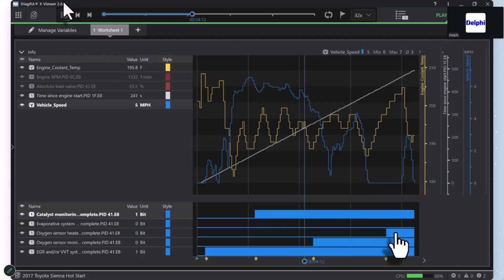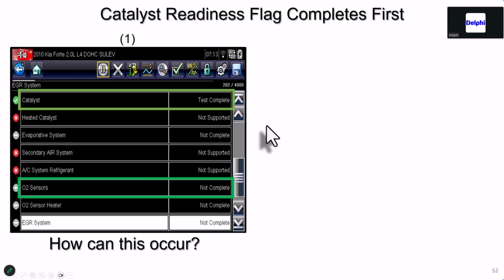I want you to think about what your objective is and think about how that O2 or that test might run, and don't get locked into a pattern. I've got a lot of these, and you'll see that trying to use the pattern is not always the answer. What was the startup temperature? How long had it been sitting? Did you start it hot? So that can affect it, okay?